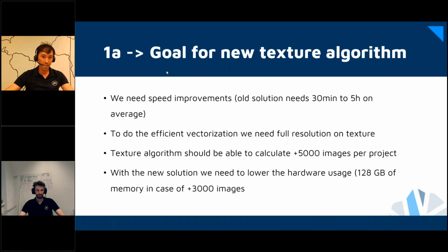The second strong point is that most of our customers are surveyors, construction workers, miners, architects, and they do a lot of vectorization inside of 3D Survey, or they export the data into other CAD software and do the vectorization. We know that we need the full resolution on textures. The input image resolution should be the same as the mesh resolution. Our goal was that you will be able to see clearly road marks, curbs, manholes, building corners, or anything like that.